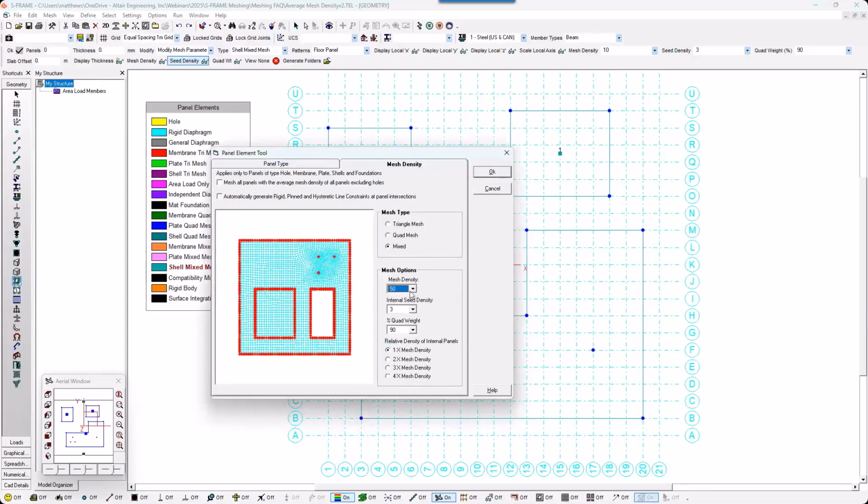It's much denser naturally. We also have one whole panel, and we have one internal panel that might have a different density, for example. So we can have a different density in that internal panel if we really wanted to. Let me back this down a bit and say I want internally a finer mesh around that internal panel. We can also control the seed density. So like we saw, we have these 3 internal nodes in this demo panel that we have in this dialog. And I might want to back this off and say, I want to use a seed density of 1.